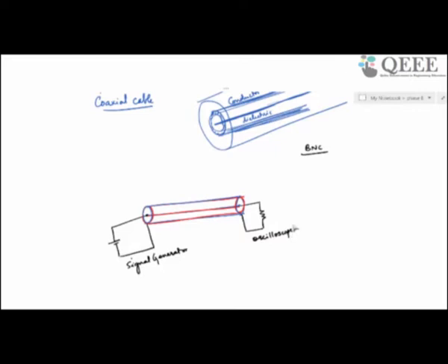I could connect a DC source to the oscilloscope, right? So I'll get a DC value. How does the current flow through this? From the positive, it goes through this, goes through the oscilloscope resistance, and this is the return path.